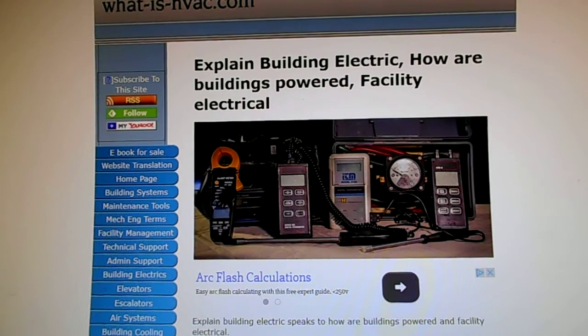Power transmission, for the most part, uses three-phase alternating current, AC, and the electricity is transmitted at very high voltages of 110 kilovolts and greater, which reduces the energy lost in transmission. Power is for the most part transmitted using overhead power lines, although sometimes underground power transmission is used. The underground transmission is more costly and has technical operations, but is sometimes required for specific purposes.